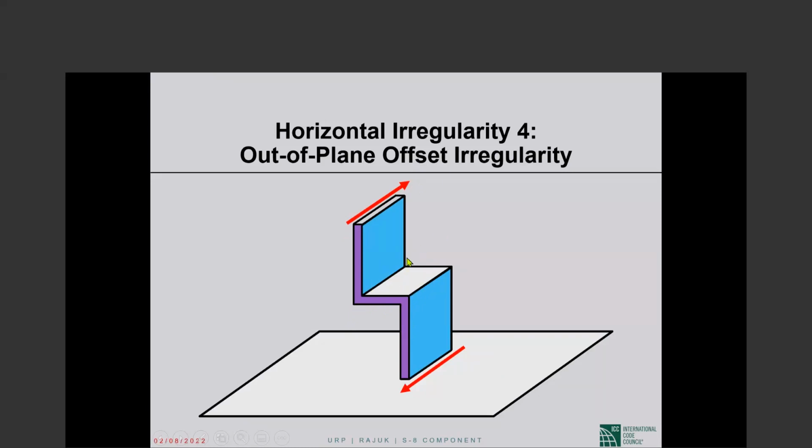So there will be this shear, there will be that shear, and then there will be shear in the diaphragm. This is called a transfer diaphragm, when the diaphragm has to transfer the shear from the base of this wall to the top of the continuing wall. This transfer diaphragm has to be treated properly in design. Those transfer forces have to be treated properly.